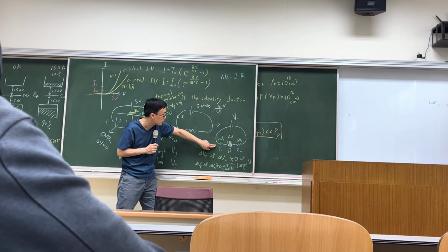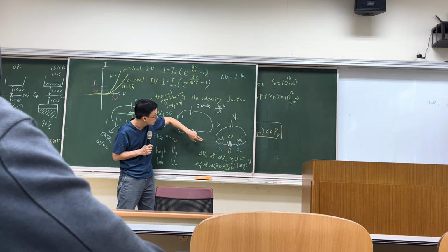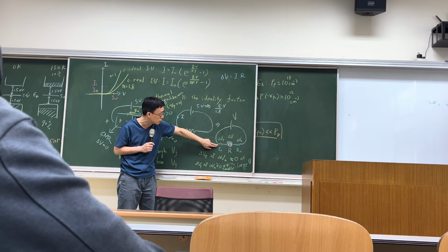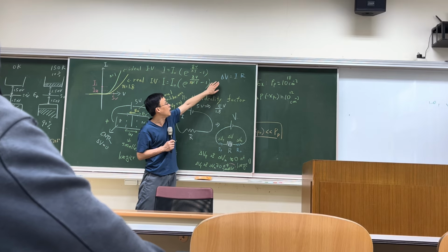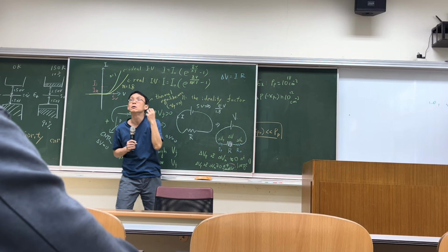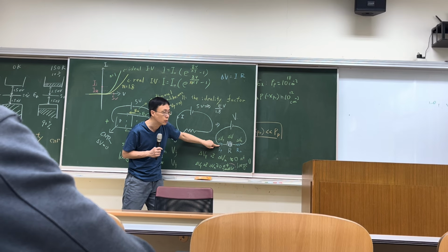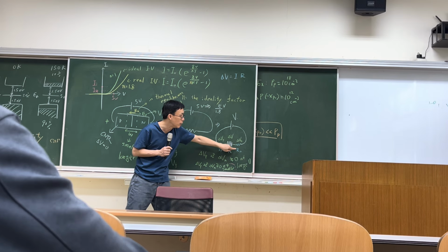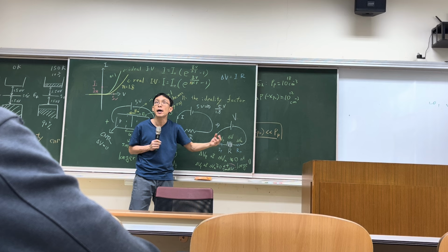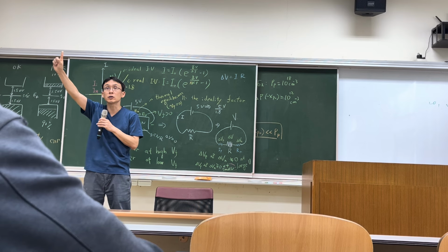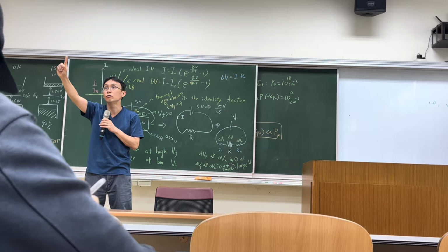So with the voltage drop, when the current runs through the resistance in the quasi-neutral region, the N region and P region, you will eventually have a non-zero voltage drop in the P region and the N region. And then, if this happens, the first assumption is no longer true.